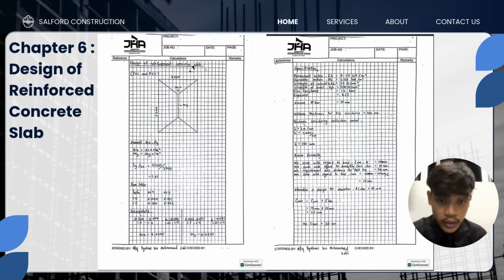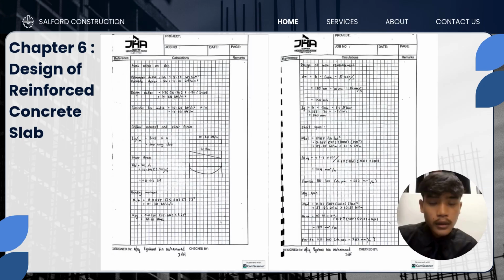And then after that, we need to assess our durability, which is the ceiling, the fire resistance, and so on. After we assess our durability, we will get our value for the C nominal, and then we use the C nominal for our next calculation. After that, we need to assess the action on slab. We need to use our GK and QK, find the design action, consider it as 1 meter width, and then find the critical moment and shear design.